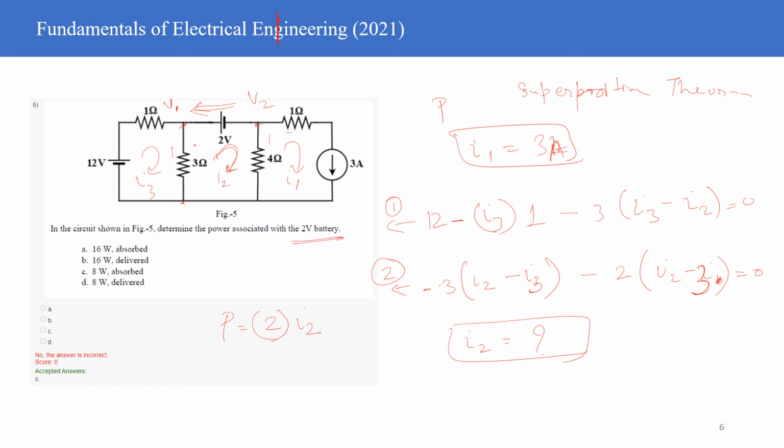So the current is flowing in this particular branch. I have taken the current direction like this. Let's say I'm moving, taking the effective current like this. Then the value of the current will be equal to, Hassan? The current is in this direction. Then the value of the current in 3 ohm will be equal to? Minus 3 (I2 minus I3). Right. So I2 minus I3, right? Yes, sir.